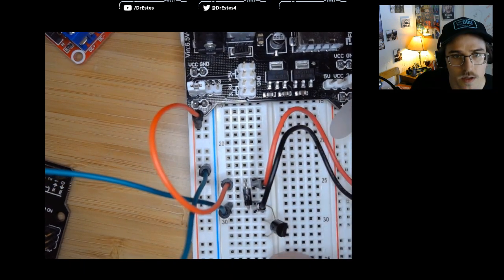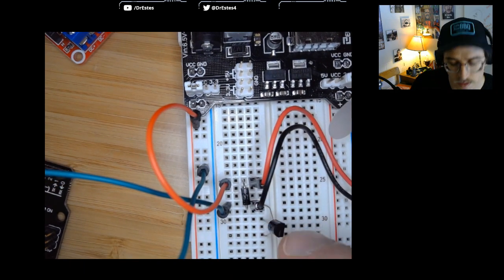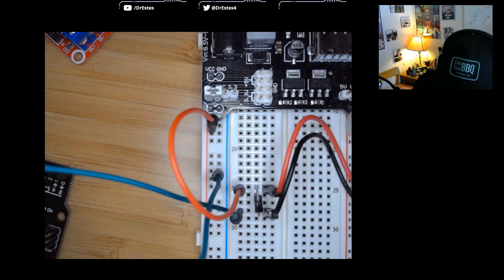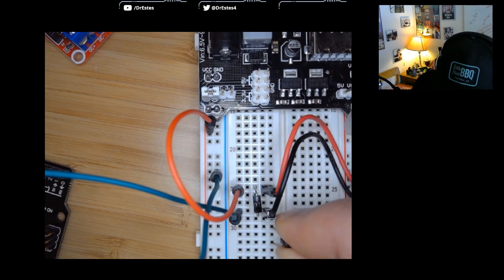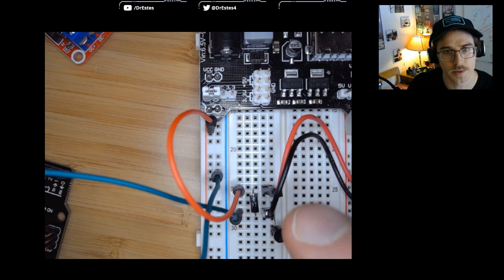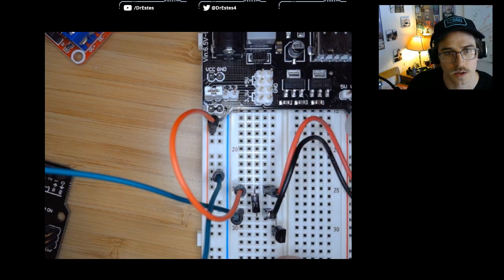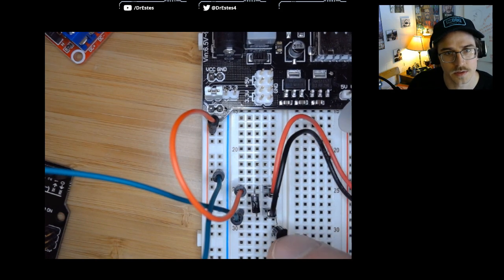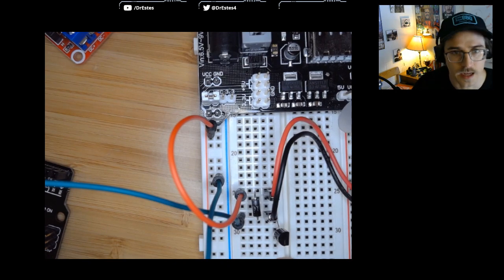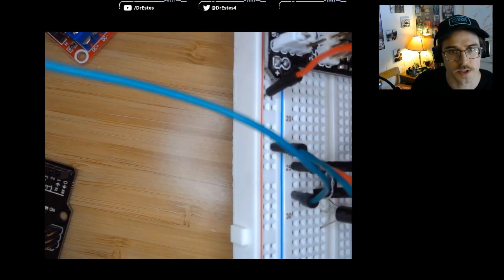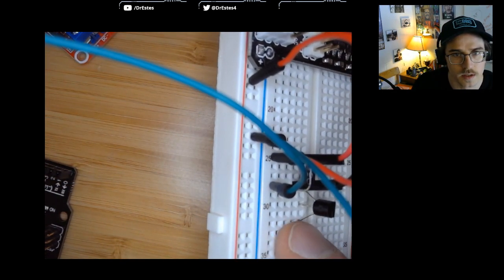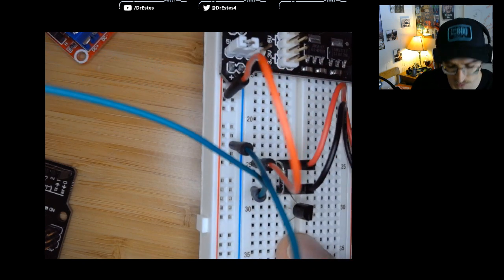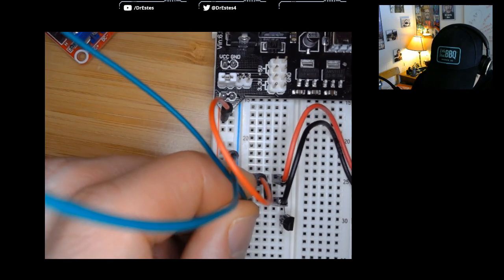And once again, you can tell because the transistor has this crescent shape. I'll make sure the documentation shows you. So I've got the negative end going in there. Down at the bottom, you can see it's got 3 legs: collector, base in the middle, and then emitter. This emitter should go back to ground. So let's put...